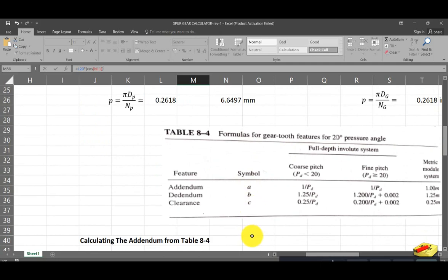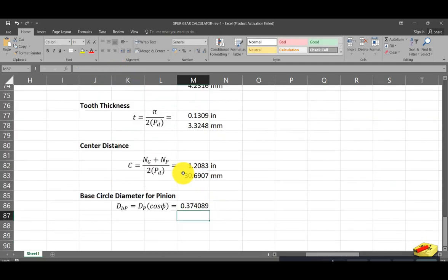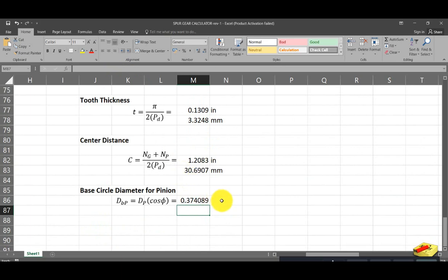Going back to the equation there, I'm going to press enter here. You will notice what we are getting. We need to convert this. Our angle here must be converted into radians, or the value of the angle must be converted into radians. So what I'm going to do is double click this one, click here, and type a string here, radians.